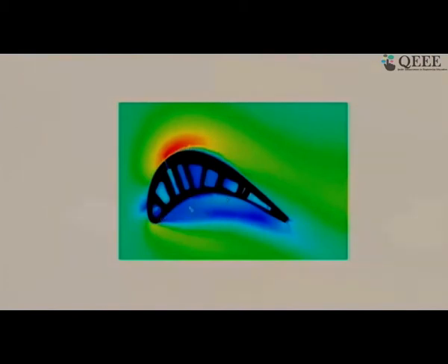But the thing is that you cannot allow the metal temperature to go that high. It will melt. So at 1600 degrees Celsius here, maintaining a material temperature below 1000 degrees Celsius is a big challenge in cooling. So one of the designs of this blade is that inside the blade there are cavities which run the entire height of the blade.